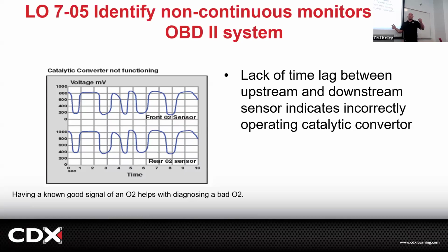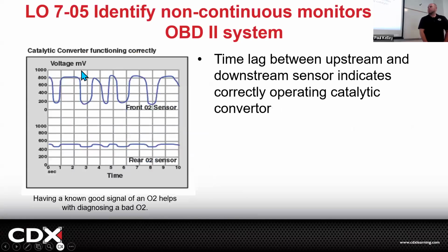But that's, no, catalyst low efficiency. So now we're going to dive down to this one to make sure you really are grasping the monitor and the input and the output, right? If it's like this, we can presume this sensor appears to be reading well. If this sensor starts to do some weird stuff, we may set a performance code for that bank 1, sensor 1 oxygen sensor. Then you'd be like, I got a code for the O2 sensor.